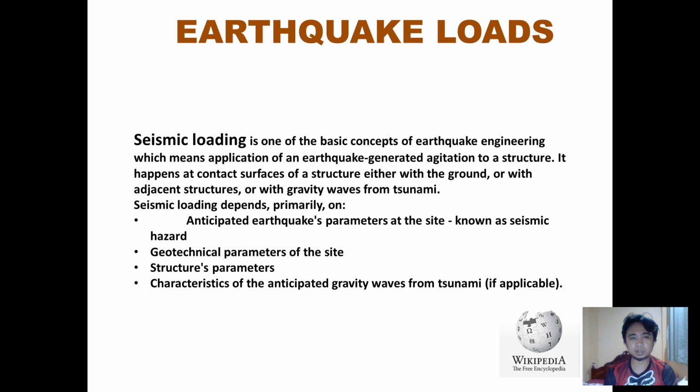So it happens at contact surfaces of a structure either with the ground or with adjacent structures or with gravity waves from tsunami. Seismic loading depends primarily on anticipated earthquake parameters at the site, known as seismic hazards, geotechnical parameters of the site, structure parameters, and characteristics of the anticipated gravity waves from tsunami if applicable.